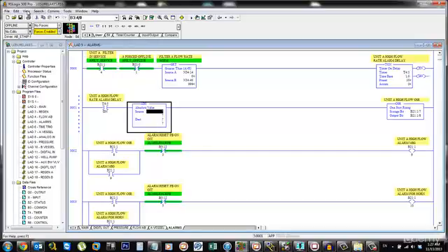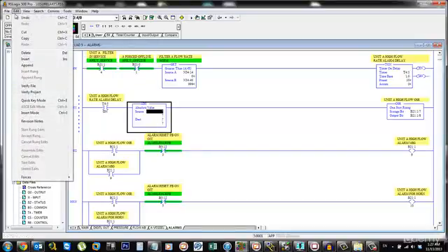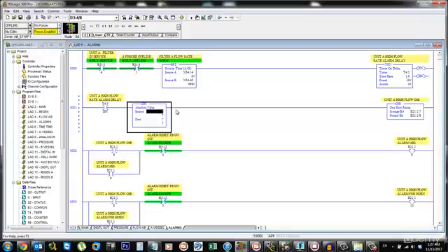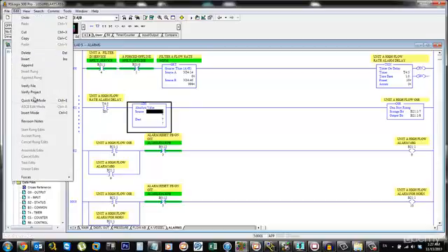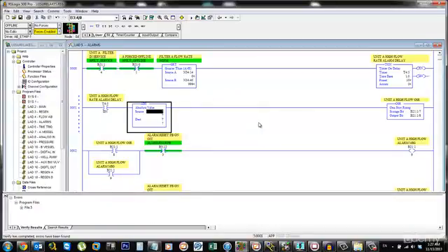Aside from those menus, we also have built into the Edit menu, Verify Project and Verify File. These come in handy because every time we write code, every time we change an instruction, we have the ability to go through and check to see if there are any problems with our program. And right here it tells me I have an error in Program File 5, Rung 1, Instruction 2. I have 3 different errors. And when I look, Program File 5, which is what I'm in now, it's my alarm ladder.